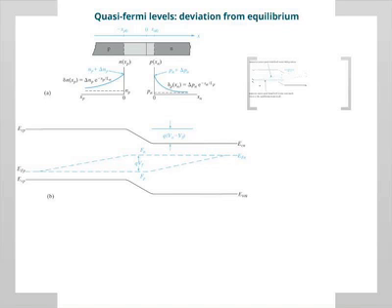But the intuitive idea is that the Fermi level follows the carrier concentration. And the fact that the Fermi level is constant under equilibrium is the fact that in the neutral regions, the carrier concentrations are basically constant, right? There's no spatial variation. The only spatial variation happens here, but still the Fermi level at equilibrium is constant across because the bands will bend to compensate for it. Okay? So the carrier concentrations under equilibrium conditions are constant. The only change happens in the depletion region. And the bands bend for that.